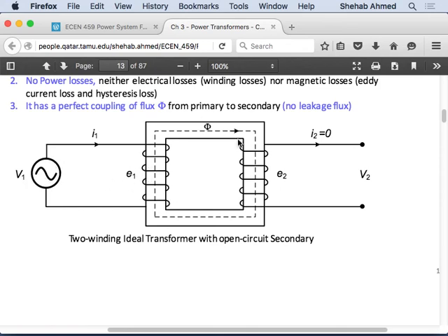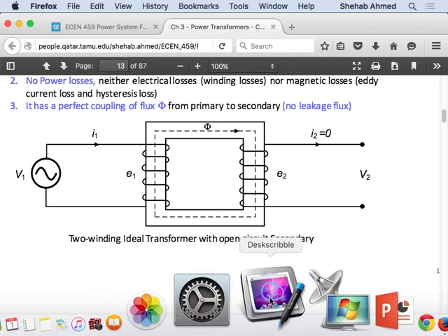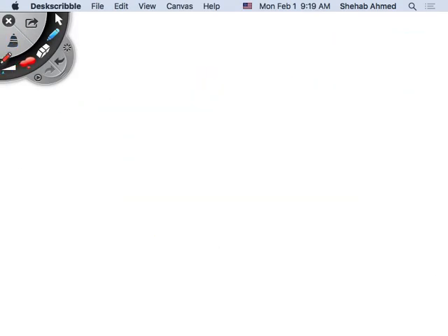How about the flux on the phasor diagram? Where is it going to be? Is the flux leading by 90 degrees, or is the voltage leading by 90 degrees? E equals N dφ/dt. So if the flux is a sine, the voltage is the cosine. So the voltage will be leading by 90 degrees. So I can draw a phasor diagram quickly, right now, for all the voltages and currents.